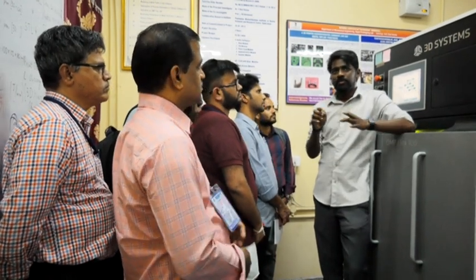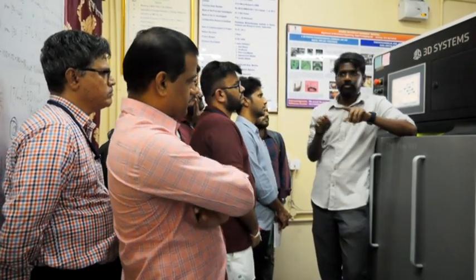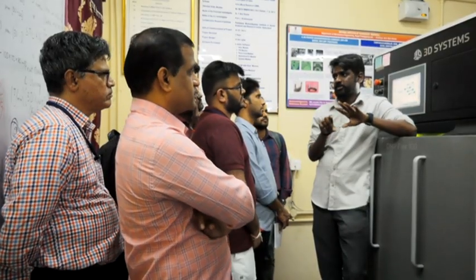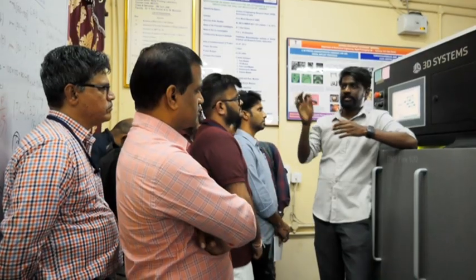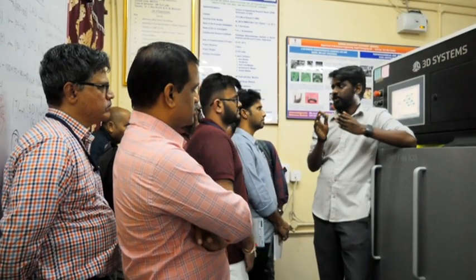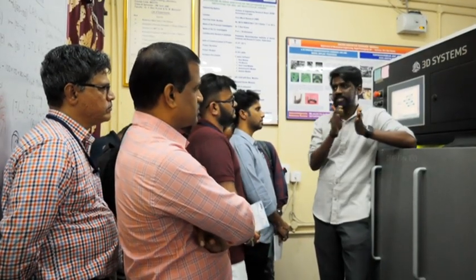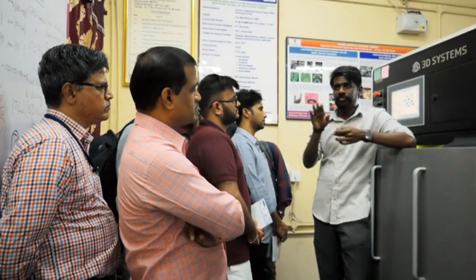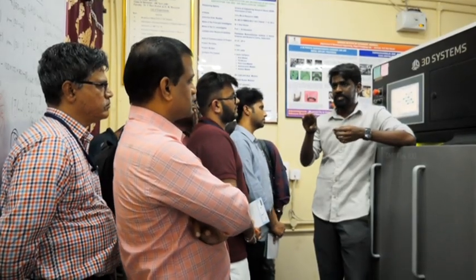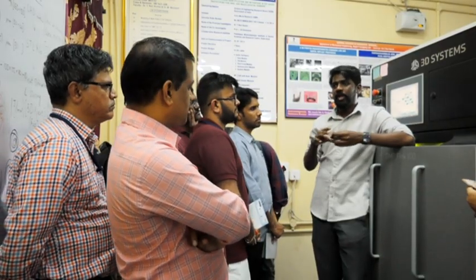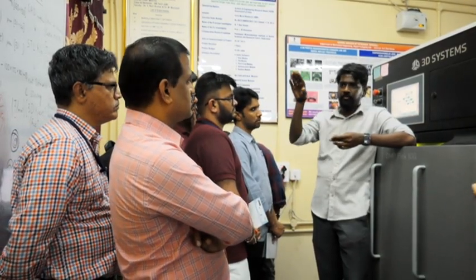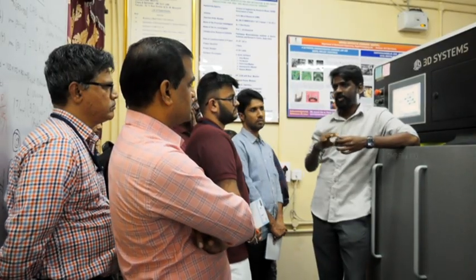Here mostly the powder particle size will be 45 microns, but the supplier will give bigger size particles. In order to segregate them, we have to do a basic thing like powder sieving. We have to use a 45 micron mesh size. Particles above 45 microns will stay on top, and the bottom side will get the particles below 45 microns.